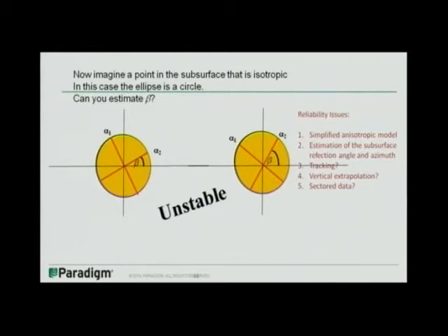The other issue is your case. I don't know the Eagle Ford, but looking at units we know from around here, they have multi-directional jointing systems. Some of them are bed limited, some of them are non-bed limited, and those have internal rotation of stress field during time. So how do you handle that, since those would result in an average vector that is not necessarily representative of the actual directionality of the joint system as it would be reflected in the anisotropy?